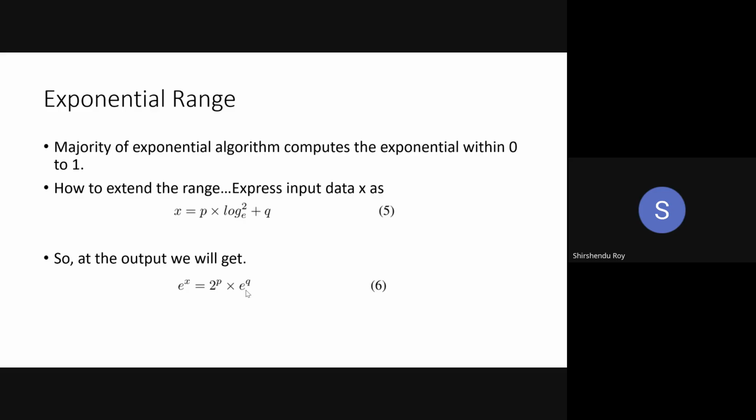The problem in the hardware is that expressing any value x in this format, equation 5, is very, very difficult. What is the first technique we can use to express any data this way? We have to divide x by log 2 or use repeated subtraction. So either we have to use a divider, or we have to wait for subtraction, subtraction, subtraction. It is very time-taking as well as very hardware expensive.